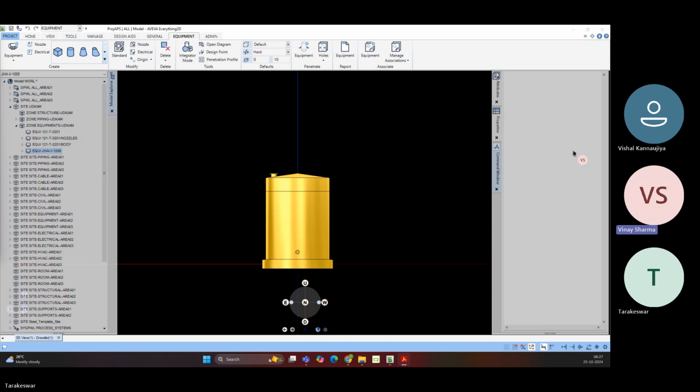Understand? Any doubt, Vishal? No sir. Okay. So for free draining we require some tapping points. What are those tapping points? Whenever you have a pipe, you don't know what it is like inside; there might be some mud, rust, or dust. Whenever the flow is going, you just provide a tapping. You open that tap, the clean water goes straight, and the rest comes out of that drainage tapping.